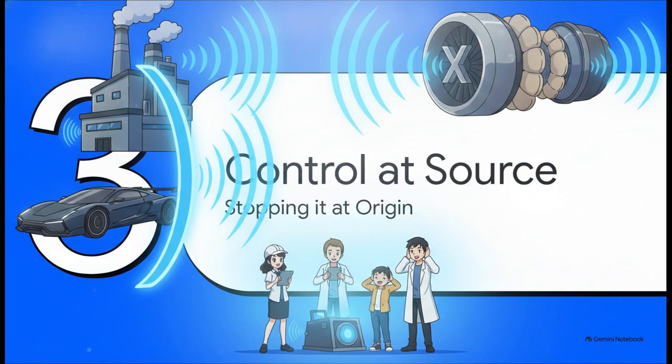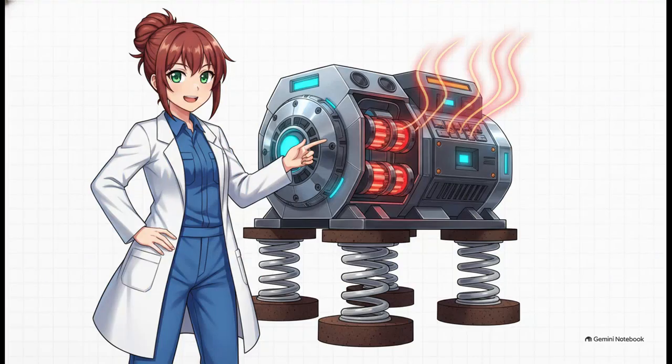Section 3. Controlling noise at source. Stopping it at origin. Let's look at our first point of intervention. How can we modify the source to reduce its noise output before it even gets a chance to travel? Well, if the noise source is a machine, we've got some highly effective mechanical solutions. For large vibrating surfaces, we install dampers. These are amazing because they actually extract the raw vibration energy from the machine and dissipate it harmlessly as heat.